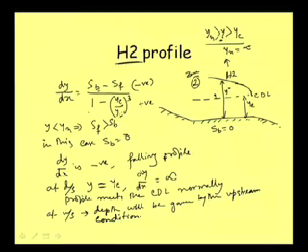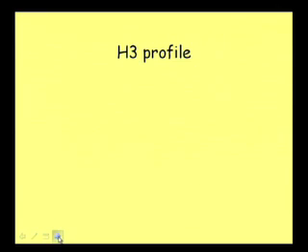So, for subcritical flow we should start computing the flow, or we can have our control section at this point, that is this depth is fixed, and what will happen at the upstream point, we need to compute from this side, and then only we will get the depth up to this point. Well, that will be coming in a more detailed way. Now, having this characteristic of H2 profile, we can now go to the characteristic of H3 profile.